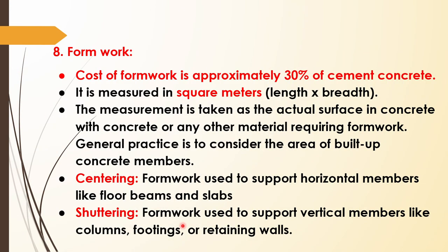The next item is formwork. So I think you know what formwork is. The cost of formwork is approximately 30% of the cement concrete. Whatever the amount of cement concrete we are using, 30% of that will be taken for calculating the cost of formwork. Normally it is like that. Now the quantity of formwork, how much formwork we have to do, is calculated in square meter.